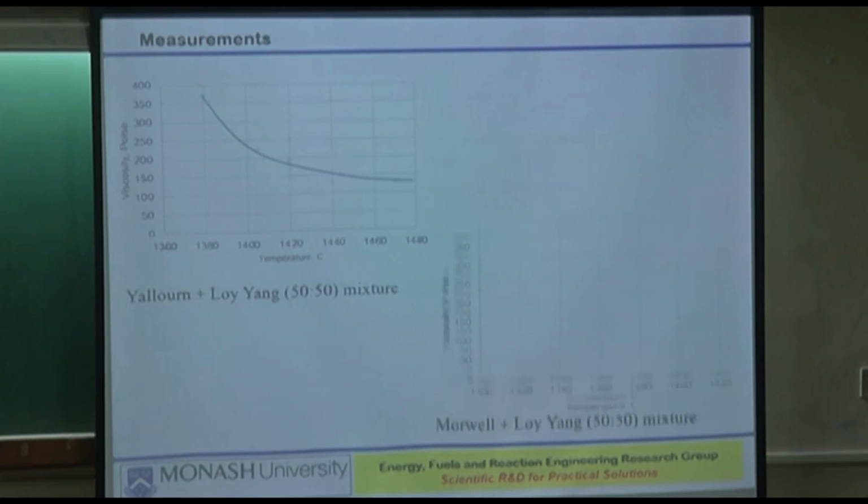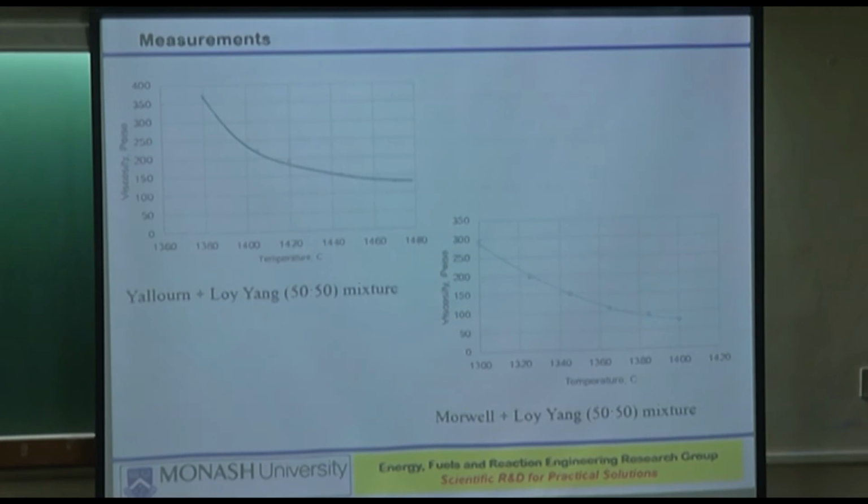And so we eventually said that, look, this is the temperature region for this and this coal mix, this and this ash mix of this type and that type of coal, and this is where you will get your 100 to 250 poise viscosity in the temperature range.